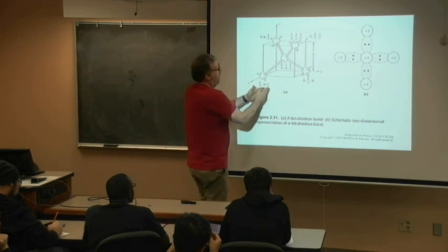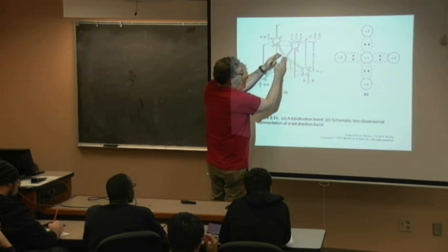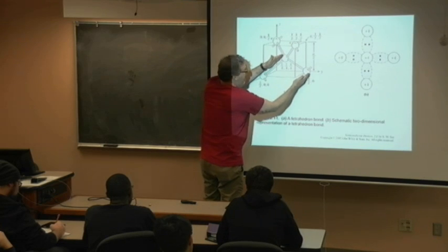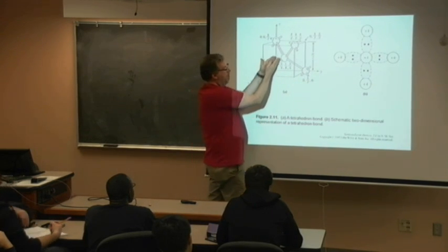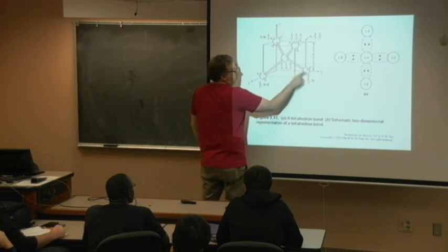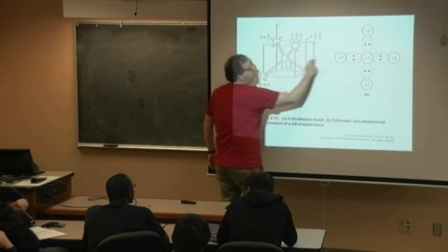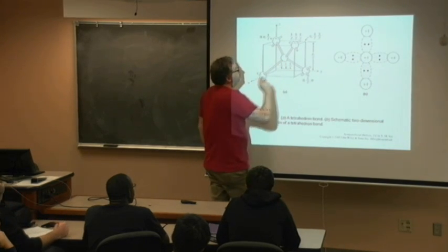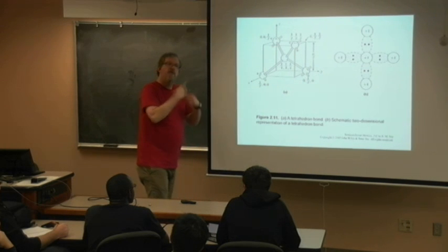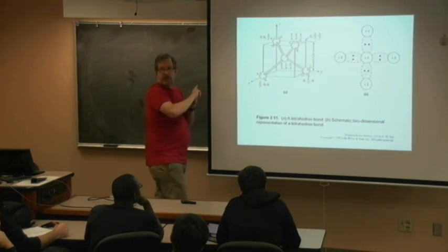So that now sets in motion that I have this bonding, I have this interatomic spacing that is set, I have a directionality to it. So as I start to parse this together into the semiconductor, I'm going to have certain interatomic spacings going in this direction, certain interatomic spacings going in this direction, certain interatomic spacings going in that direction, and I'm going to have a unique solution in all these different crystallographic directions.